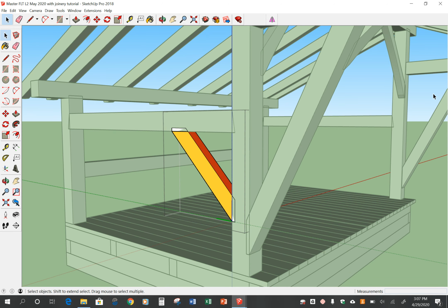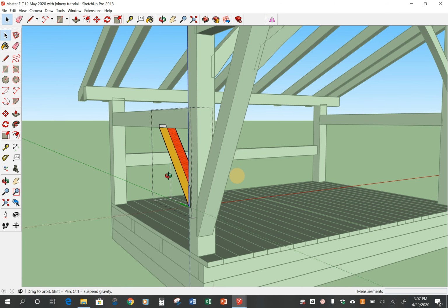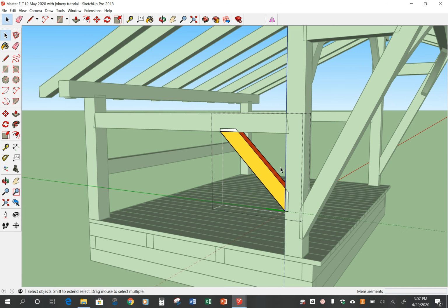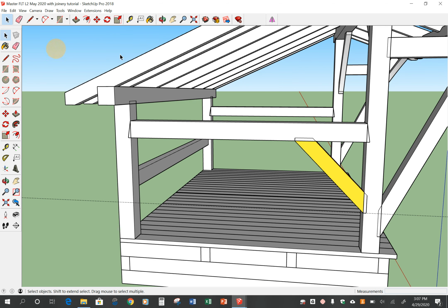I have not done anything on the inner face or the under face. I just colored the outer and the top. Click out here. Now remember, I have my 2-foot guideline here. Let's pull a 2-foot guideline from here because the next brace is going to want to be 2 foot in that direction. So I could use my move copy tool and I could grab this, zoom it in a little bit.